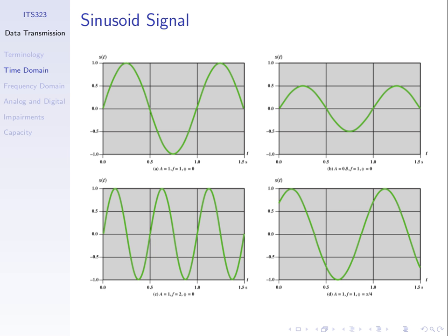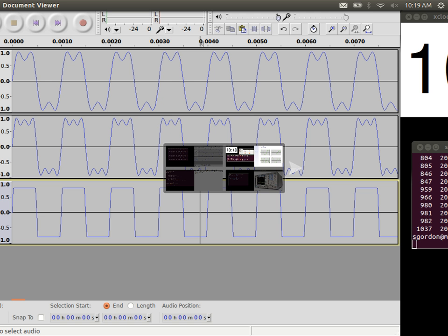If we shift the phase by pi, here we go up at the start. If we shift it a bit more, we'd go down at the start. By using a different phase, we'd get either the signal immediately going up to the high point to represent a bit 1 if we want to transmit it, or, if we want to transmit a bit 0, we'd use the opposite phase and transmit down low at that point. So our transmitter changes the phase as we have different bits. That's just one example of how we can do it.